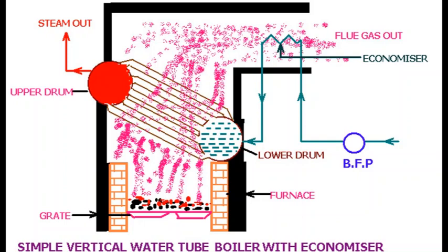As we know, it is actually economizing the fuel cost, reducing the heat loss through the chimneys, and at the same time less evaporator heat transfer area is required, as water enters the tubular part of the boiler at a higher temperature.